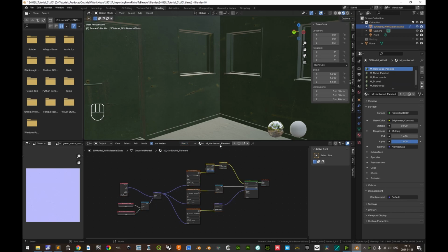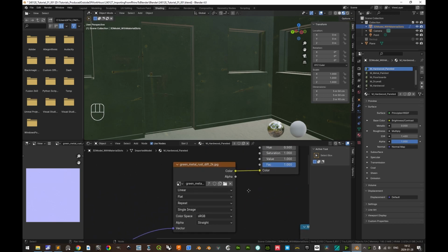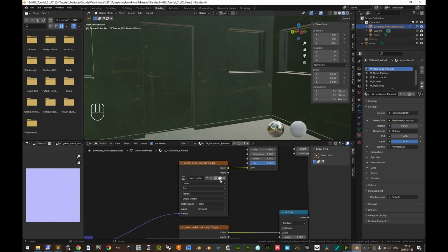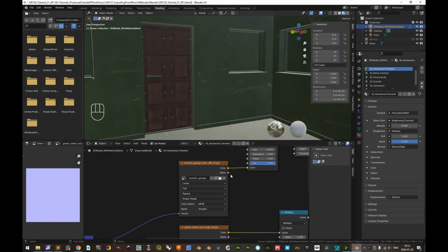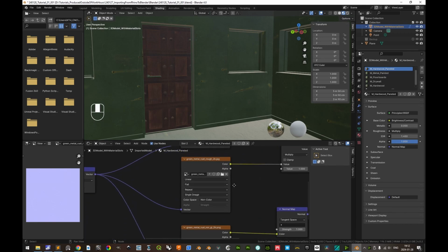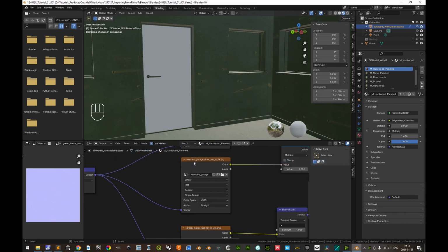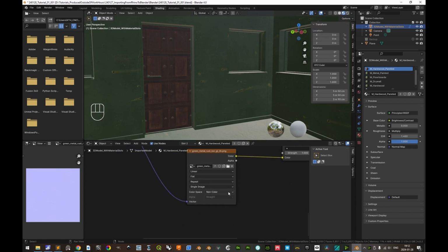And then this is the hardwood panel. So we'll make sure to open for these 3 texture nodes, the relevant texture set images. And it was this one. And this is sRGB, very good. And then we'll do the roughness. And this is very important. When you open a new texture, the color space gets its default value. Make sure to change it to the one you want, non-color in this case.